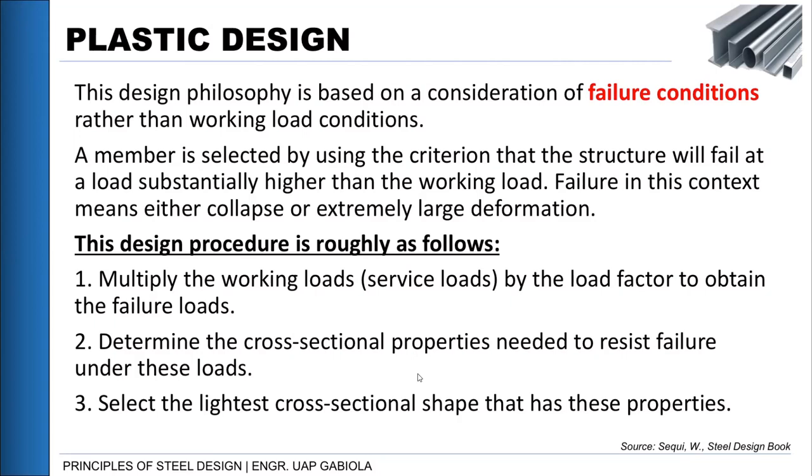Because this particular design philosophy, some say, gives a more economical section, especially when we consider the behavior of our component during plastic failure. Okay? So its design procedure is roughly as follows. We multiply the working loads by the load factor to obtain our failure loads, and then determine the cross-sectional properties according to these failure loads.